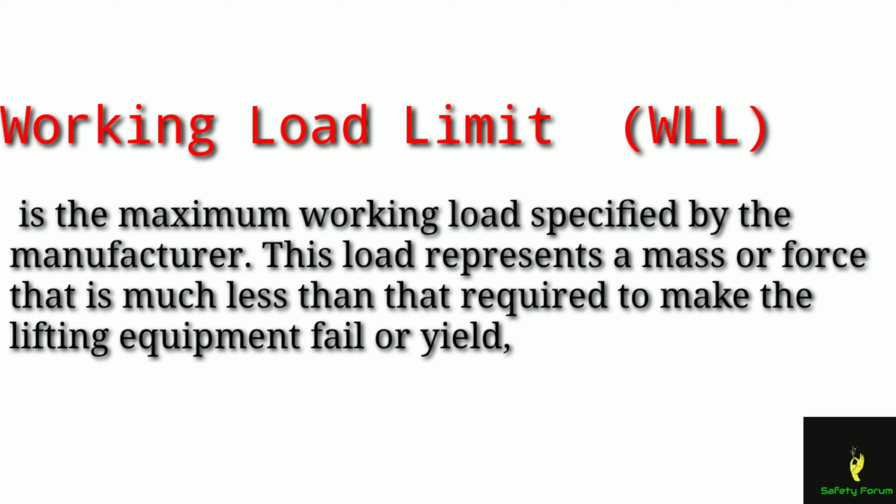So friends, as we discussed, safe working load is also known as normal working load. In some aspect, this normal working load is not safe at all. Sometimes it will vary, because safe working load is calculated by using a formula which is breaking strength divided by the safety factor. This safety factor varies. Normally the range is from 4 to 6, but in some cases, in case of heavy equipment and dangerous equipment, we have to use a value of 10 or 12. So the value of the safety factor will change, and it will affect the safe working load.